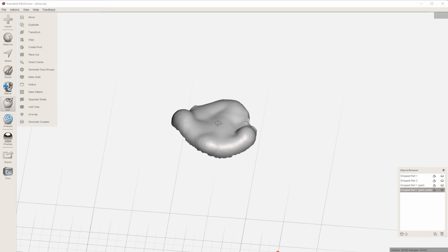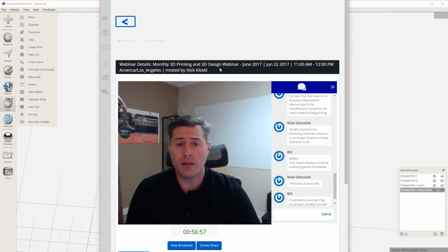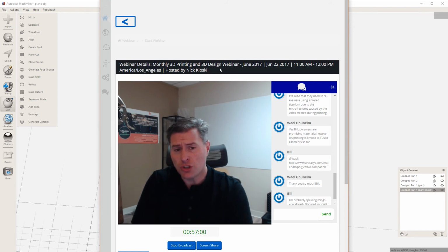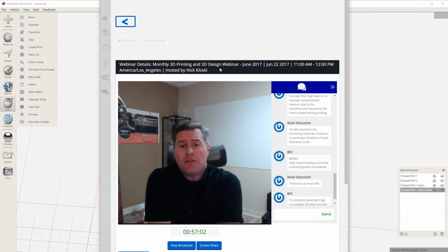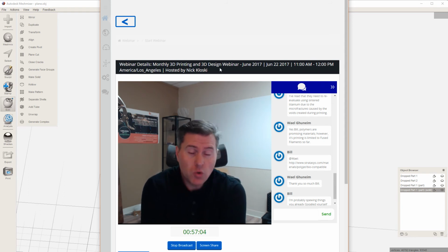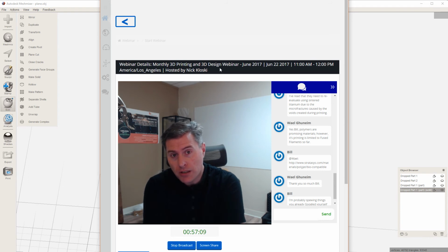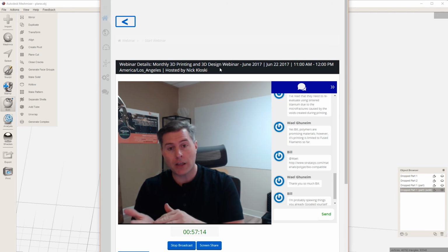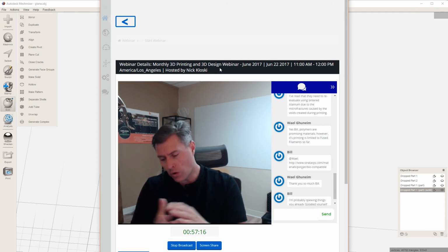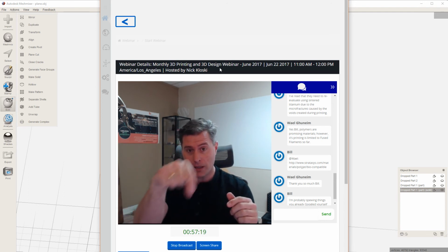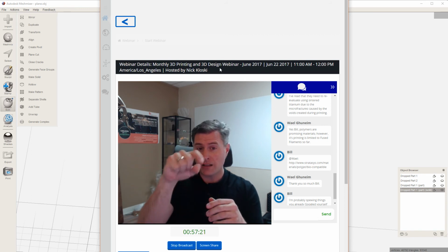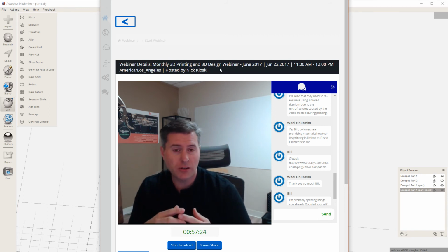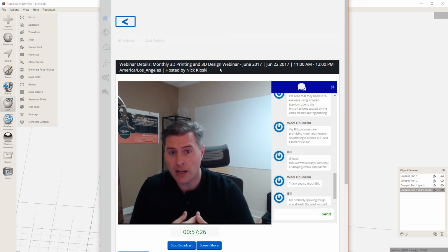So hopefully that helps answer your question about how to use tools in one places, right? If you can turn something into a cutting tool or a Boolean tool, that's how you can copy those things from one place to another. How you move things from one place to another accurately is using pivots. Or you can use the transform tool with snapping enabled if you know exactly how many millimeters things are away from each other, but sometimes that's not entirely accurate.